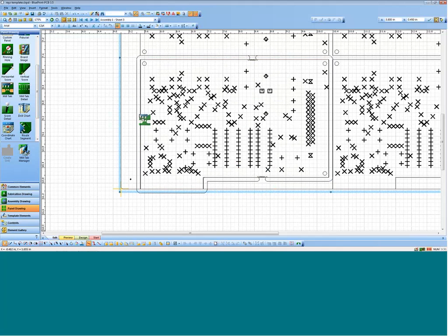And yeah, I can type in locations, but you know what? That's kind of a dated idea because really I want to just kind of eyeball where they need to be properly. And then I can just go in here and align them just by using the tools in BluePrint. So, I can move those along. I can even turn layers on and off to see if I'm hitting copper or near copper or components are overhanging. All of that's available to me because I can format BluePrint any way I want to show this.